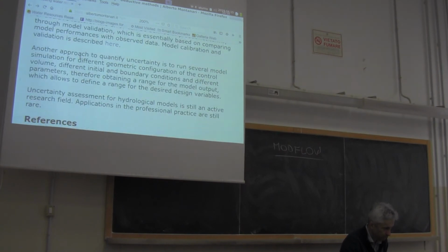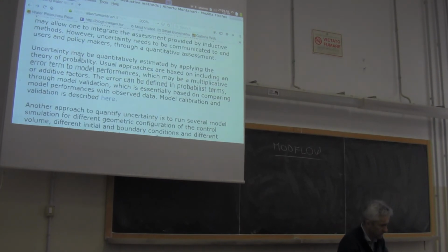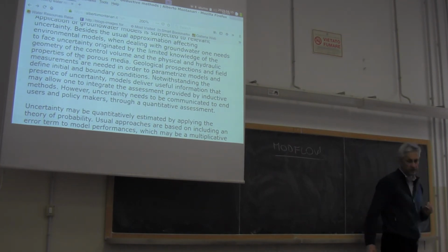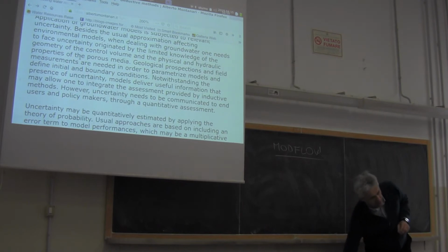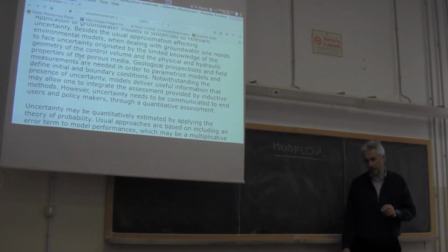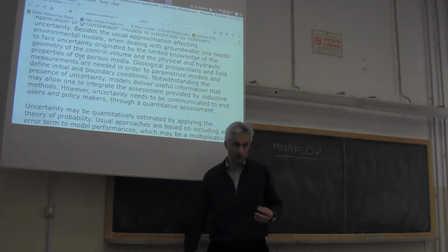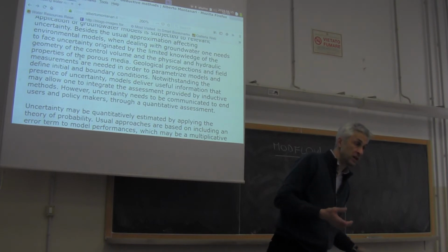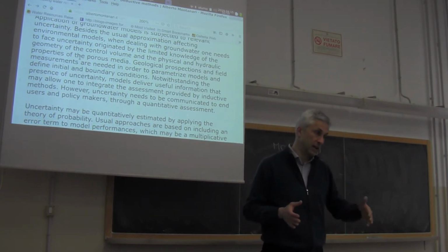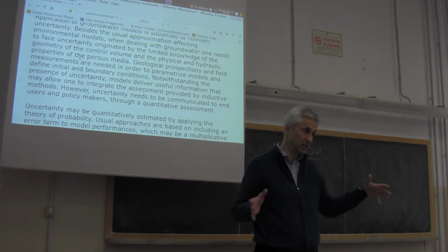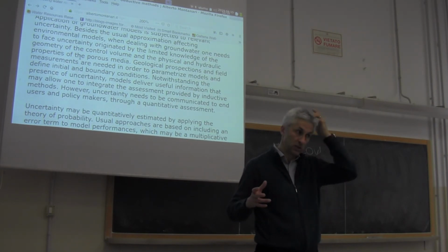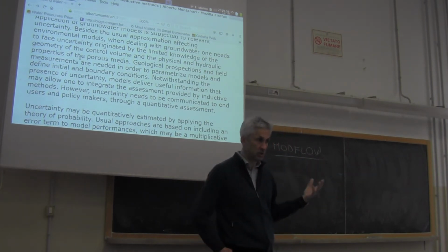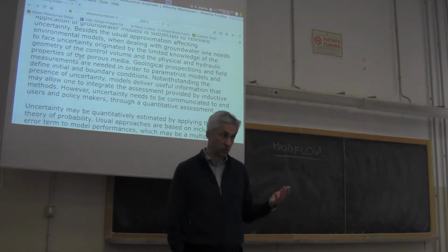Okay, just to conclude the topic, there is a discussion here on uncertainty. Groundwater models are affected by relevant uncertainty, like surface models, but in groundwater uncertainty is more relevant. And the problem is mitigated by the fact, as I said, that the flow is very slow. And therefore, if you refer to longer time scales, uncertainty is mitigated, like for surface flow. Because, as I said, describing the short-term variability implies additional uncertainty. In groundwater, we can ignore the short-term variability.